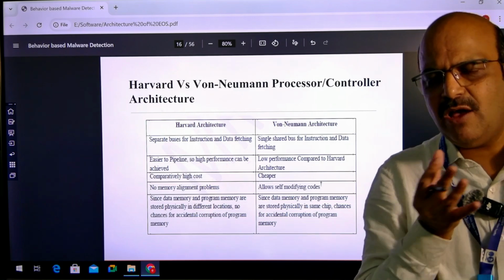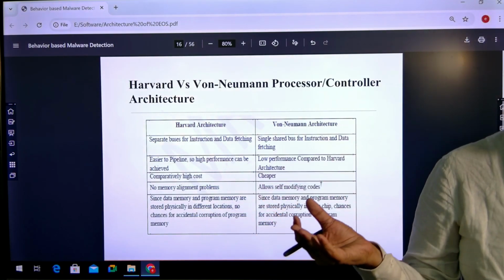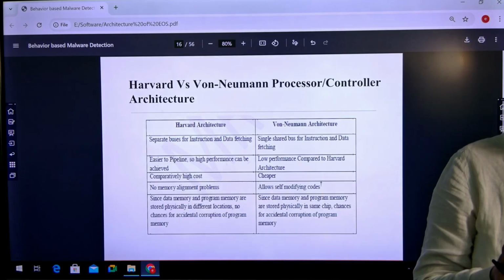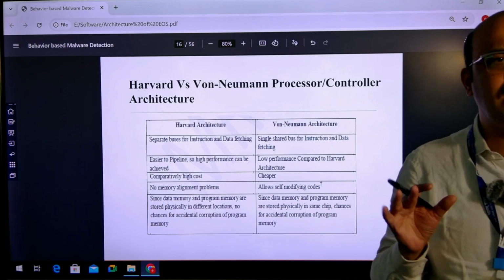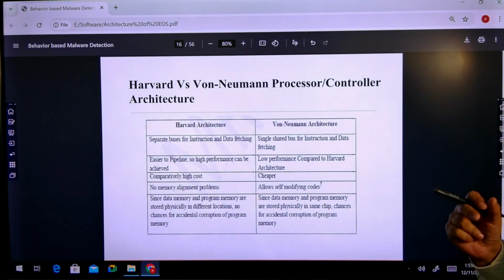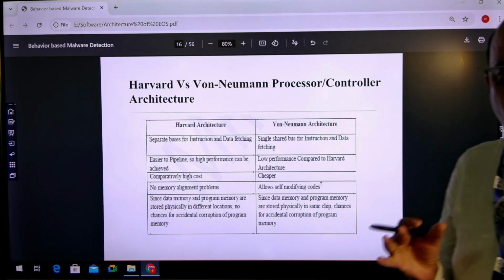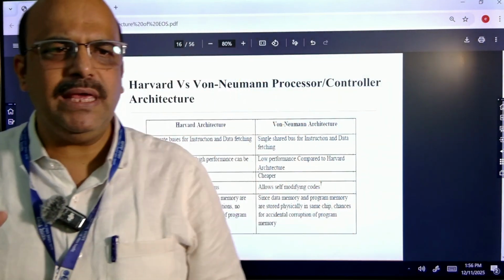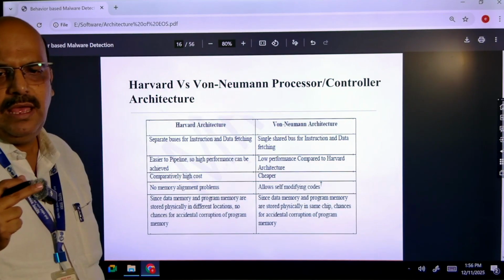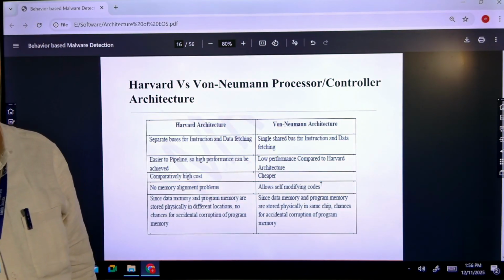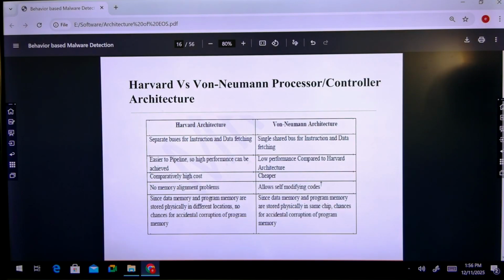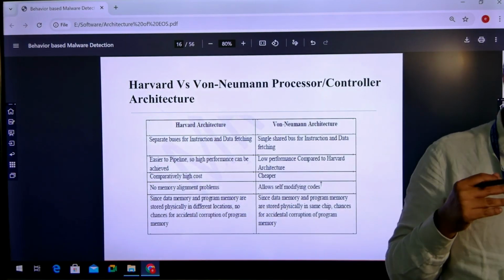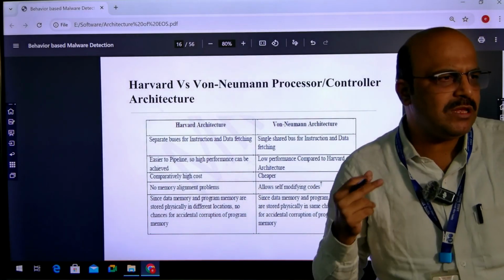Input port, we have some sensors. At the output port, we have actuators. Then we have the system core, that is the chip, which kind of controller we are using for controlling of the embedded system. Now here in system core, depending upon the application, according to that we can choose the controller. If we consider the microcontroller, as per our purpose, we have to choose the microcontroller.